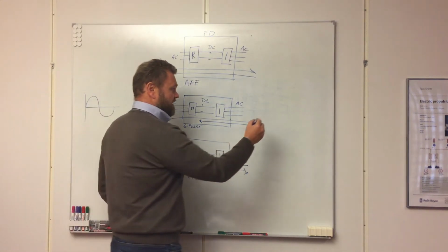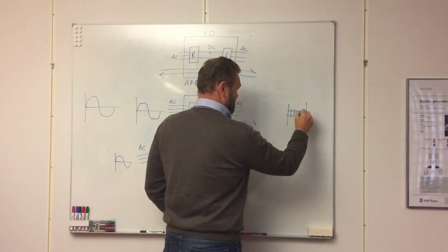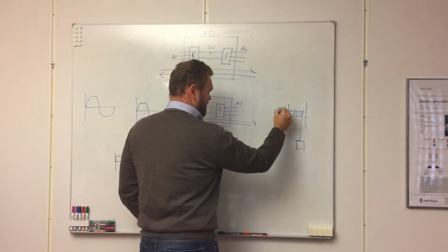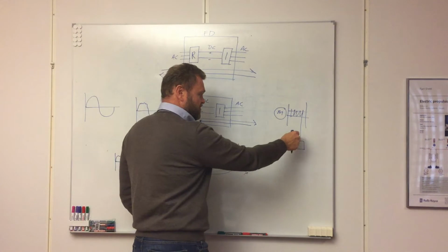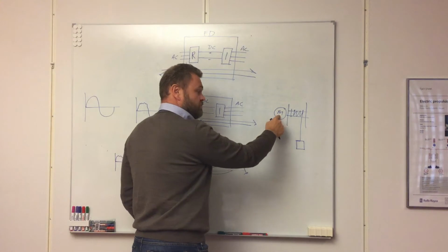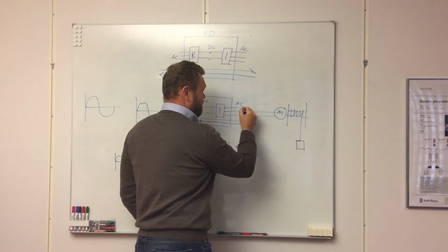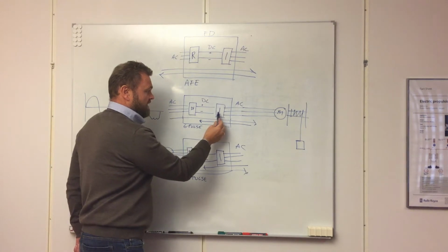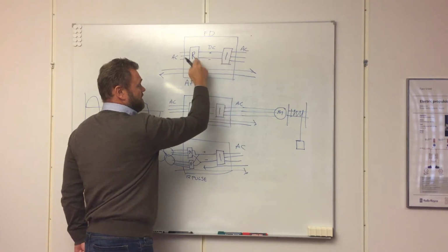Well, if you have something here, maybe a winch, with the electric motor, you need to brake the energy, because when you're lowering the winch, you're producing energy backwards, and this motor becomes a generator, generating energy backwards into this inverter, and this inverter will then rectify, because these two units are similar units.